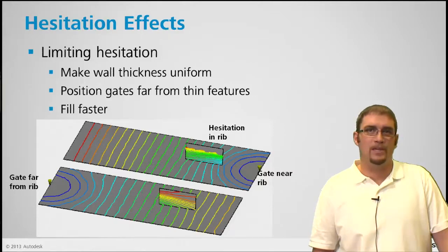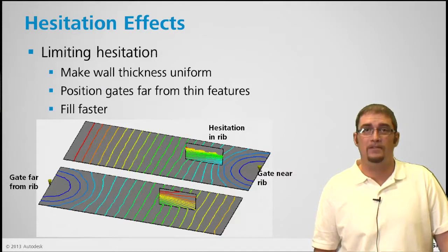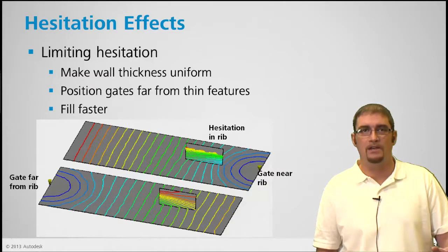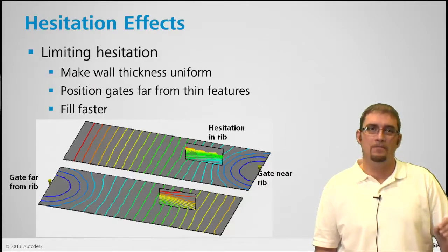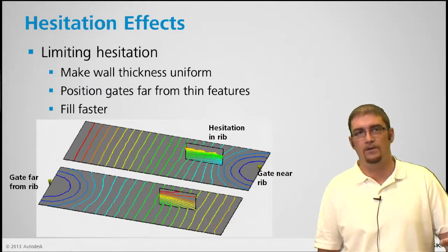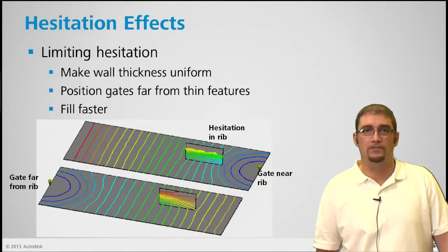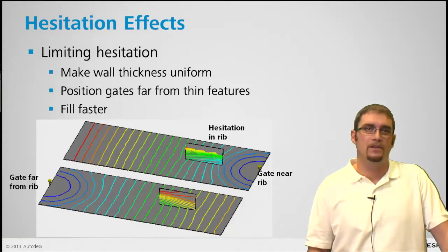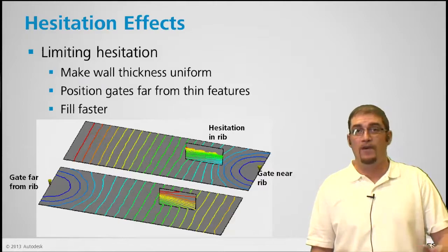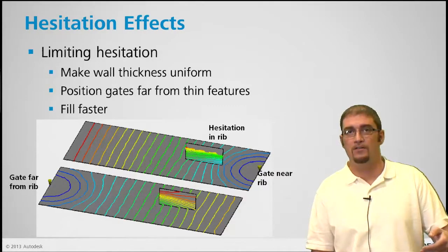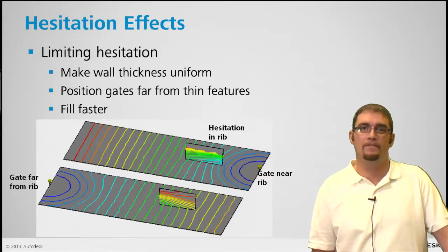know, like anything, plastics will take the path of least resistance. So the polymer is going in the gate, it's starting up the rib, but the main body is thicker, so it will take the path of least resistance and pause basically in that rib. And depending on how fast you fill this thing, that flow front in the rib could be frozen off by the time it backfills and tries to fill it, and then you get a short shot.